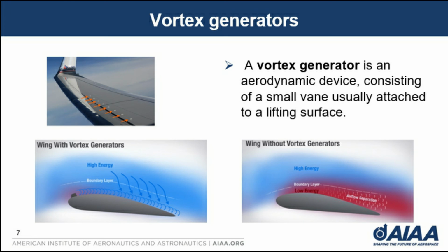The next method will be vortex generator. Vortex generators are commonly used in aircraft to improve the lift coefficient and drag coefficient. In this study, the vortexes generated from a modification in the form of the vortex generators are analyzed, which has already been investigated. The process is to analyze a NACA 0015 wing profile with and without the vortex generators using a wind tunnel. This is done because having upgraded knowledge about the vortices can give greater control of the displacement of the boundary layer around an airfoil, and this brings many benefits to the aircraft.